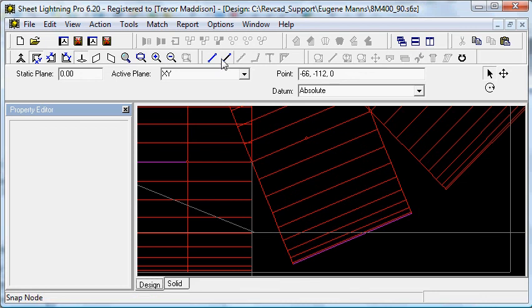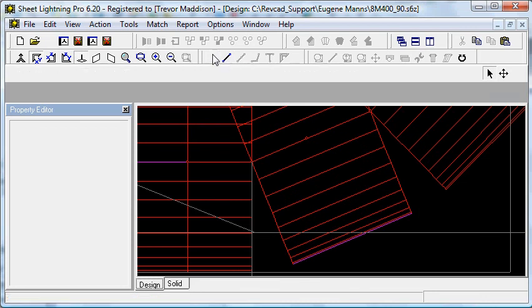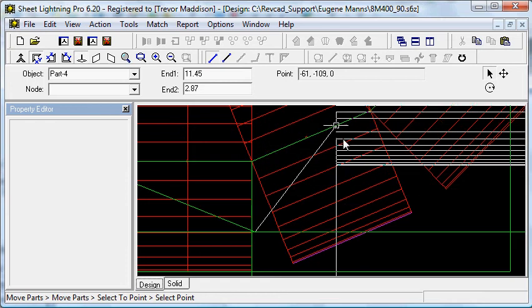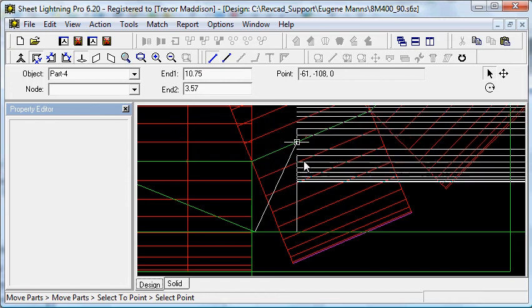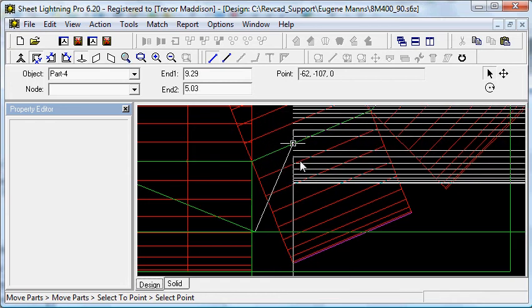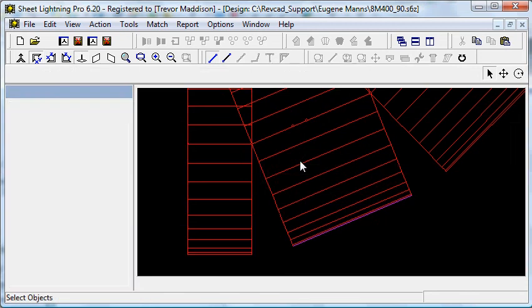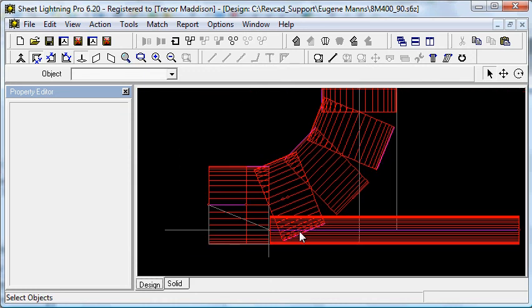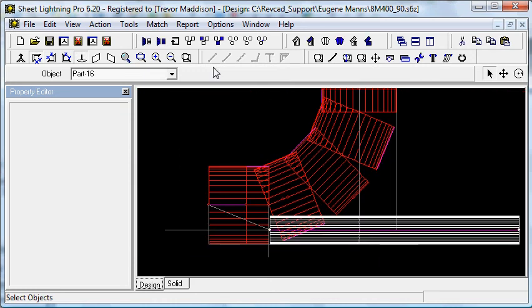What I'm trying to do is form a T with that. So I press snap to a center line. You can see the center line of this piece, and I'm dragging now along there. It's restricted to that center line. So I find a position along there, anywhere really, and press OK. And the thing is, the part didn't stay there now, because this is a complex link. It formed the intersection, but then it took it back to its original position, because it knows it is already linked into this design.